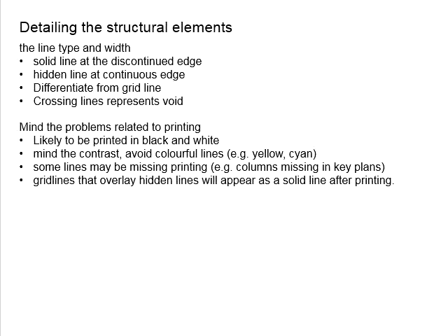The moral behind this story here is you will need to test print several pages of your technical drawing and ask somebody else to check on your behalf. Check every single aspect. Is it comprehensive enough? Are the lines contrasting enough? Any missing lines? Any overlaying of the grid line and the hidden line? You need to make sure the information is effectively delivered as per your intention. You don't want the printing to be one of the reasons that you give wrong information to the contractors.